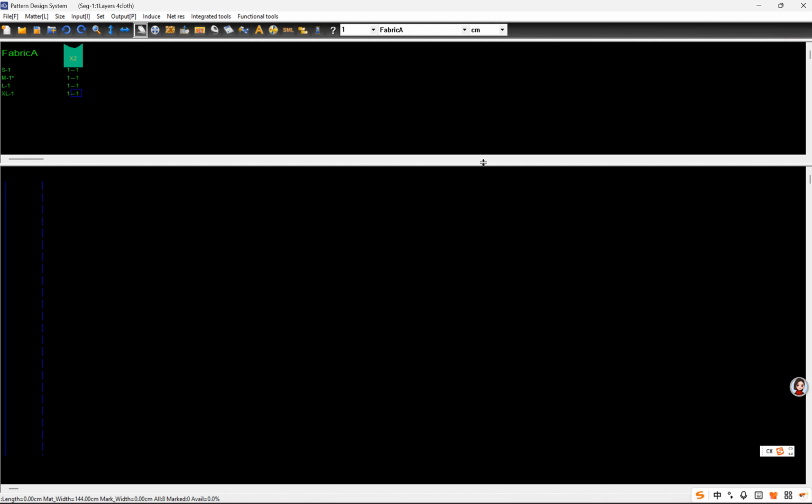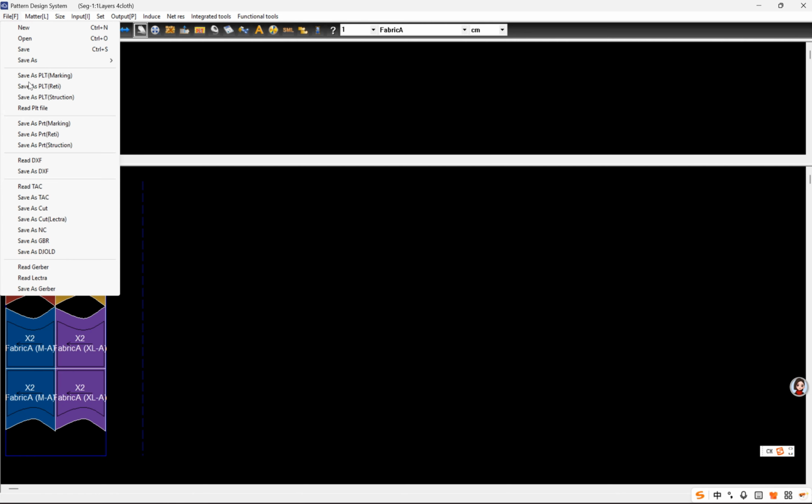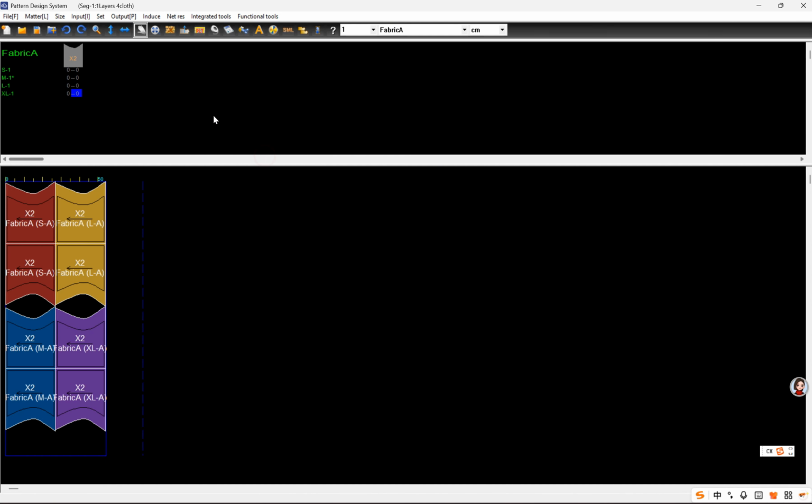and setting pattern piece attributes are performed in the pattern mode. And the mark mode. In the mark mode, after completing the drawing, arrange the pattern pieces, and then output them to the printing center. Save as PLT document with the plotters. And go back to the design mode.